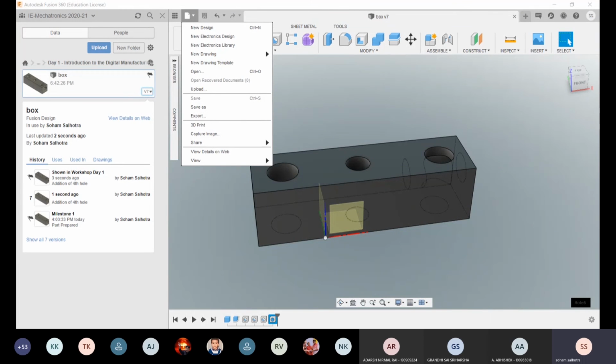That will inherit both the version history and the design. And you can just rename that file with the name of the second branch that you want, like for example, branch box test. So in that case, I'll head to save as and save that as a .f3d file on my computer. Then I'll import that back in and save that as box test, for example, and then I can make the changes in that branch separately.